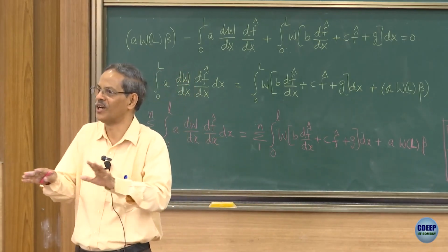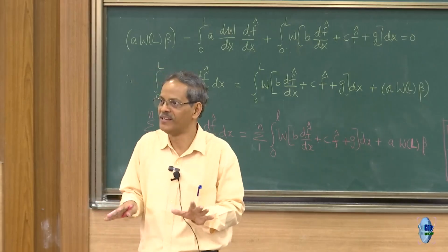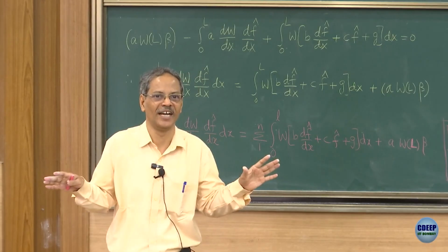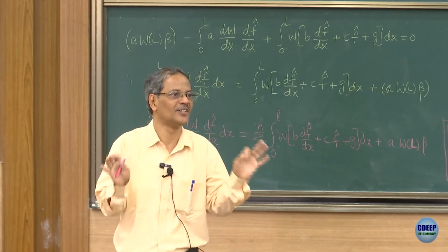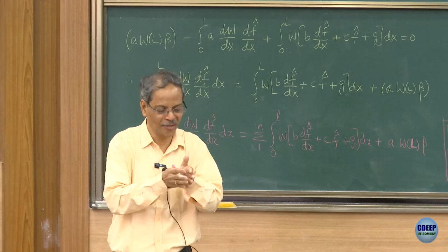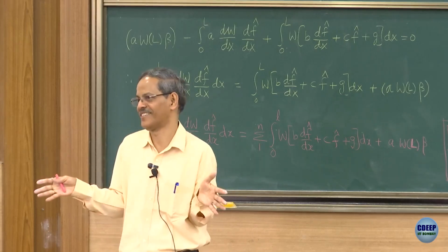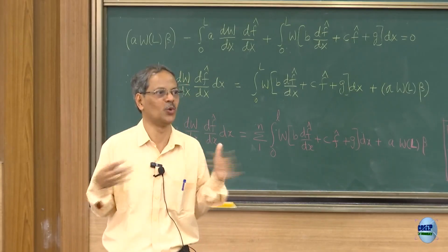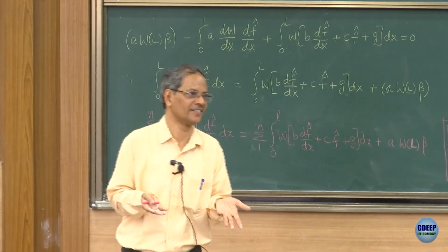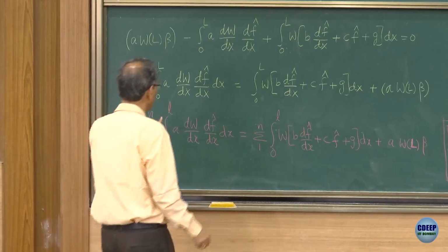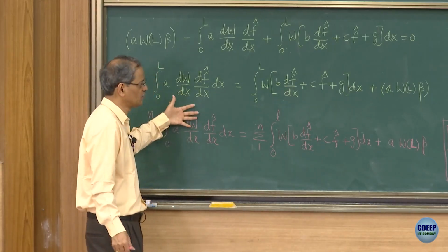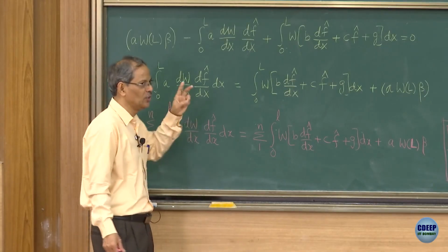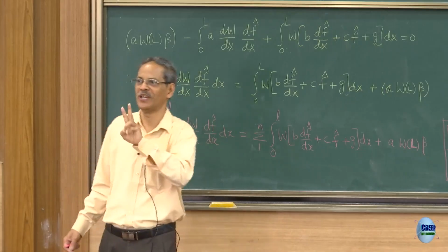I am not going to do all those complications right now. Right now I assume that everywhere from 0 to L, I am going to use linear shape functions. All the elements will be of equal size, just for simplicity, so that you get to understand how the formulation goes. Then we can introduce all these complications. So I am going to formulate this equation, how it would look if I am doing just, say, an assembly of two finite elements.